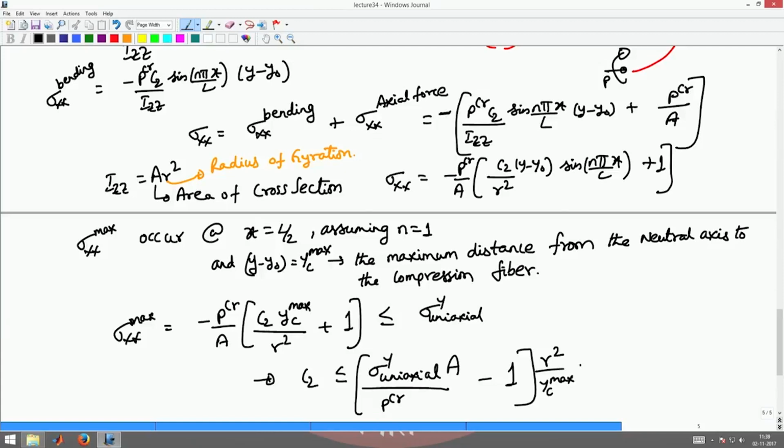Commonly it is attributed that the material failure is different from stability failure in the sense that it is independent of the material yield stress value, but the material yield stress value governs what is the maximum deflection that you can have. It is not independent of the material failure, but what happens here is because of the geometry the structure continues to deform, because you are writing the equilibrium equation in a deformed shape. It continues to deform or has multiple solutions possible arising at a particular stress value, and that hence causes the stress to exceed a particular limiting value given by a material failure limit. It is not that stability induced failures are not material failures.